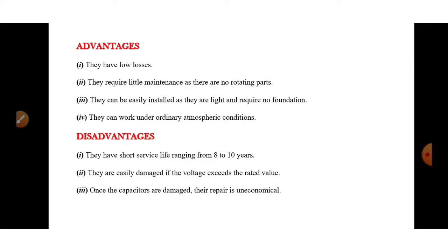The advantages are they have low losses, they require little maintenance as there are no rotating parts, they can be easily installed as they are light and require no foundation, and they can work under ordinary atmospheric conditions. The disadvantages are they have a short service life ranging from 8 to 10 years, they are easily damaged if the voltage exceeds the rated value, and once the capacitors are damaged, their repair is uneconomical. So these are the advantages and disadvantages of static capacitor. This is all about power factor improvement by using capacitor.